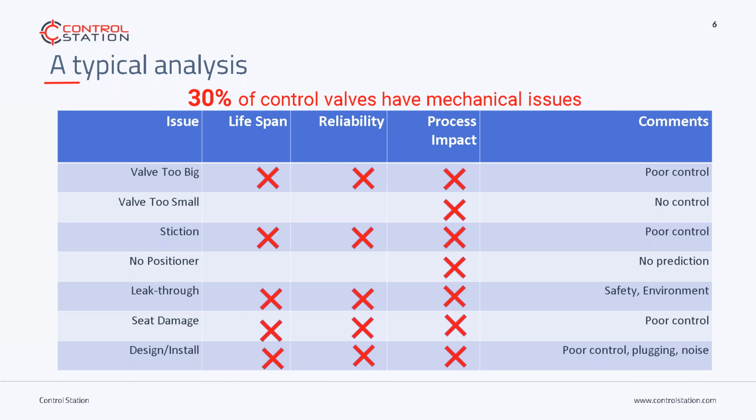Damien, what's your take? Again, a positioner is going to give you that feedback. In reality, a lot of modern valves have internal positioners so that they will correct internally rather than send the signal all the way back to an analog card. If there's going to be a positioner, it's more likely internal to the valve, so we have no feedback to that.